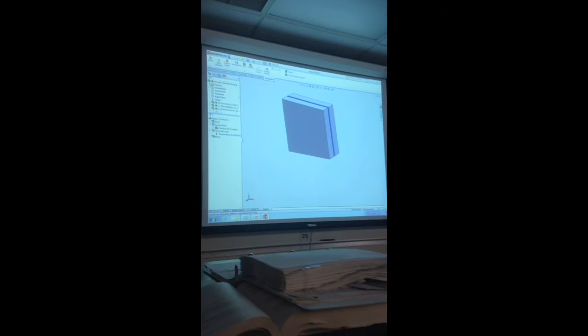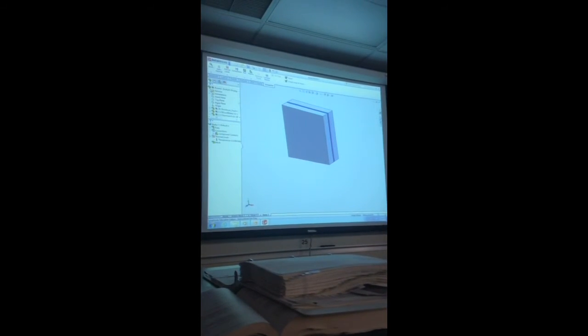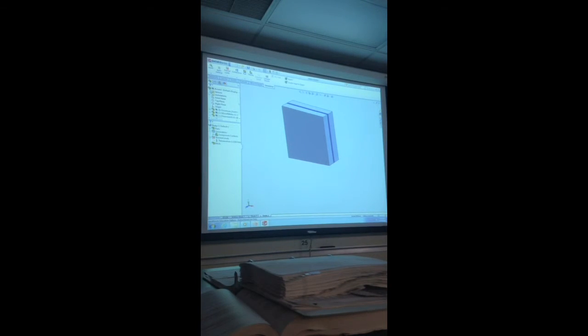Which is the first part of this design project, you've got to calculate the combination of free and forced convection. External flow. Chapter, Adam? It is. You got it right. You're good. Free and forced convection combined, right? There's Nusselt to the n equals Nusselt of forced to the n plus Nusselt of free to the n, right? You combine it that way. That's what the first part of the design project is. It's just flow over a flat plate. Wind's coming from one direction, I think from the left on this. Okay, anyway, so you've got some of your boundary conditions.